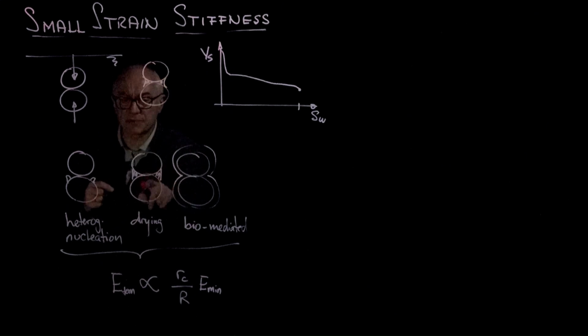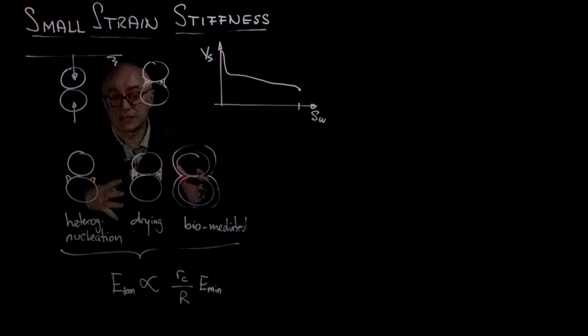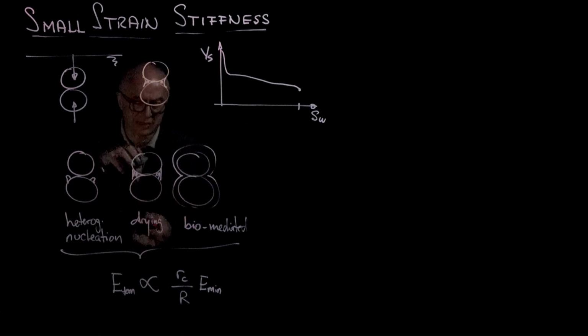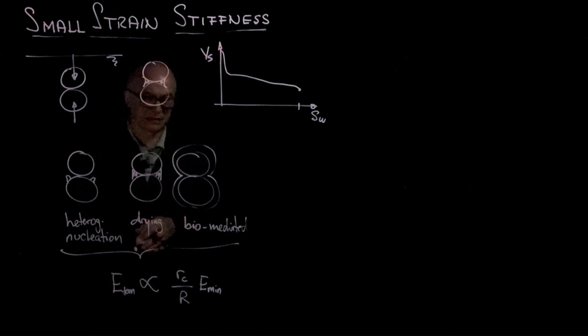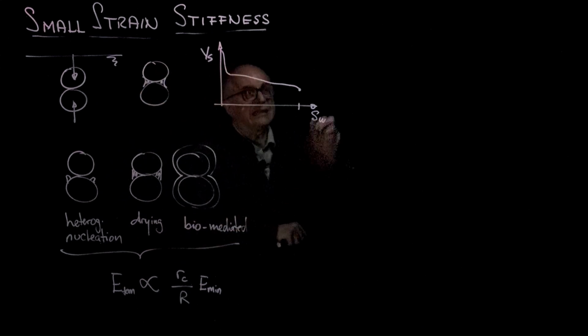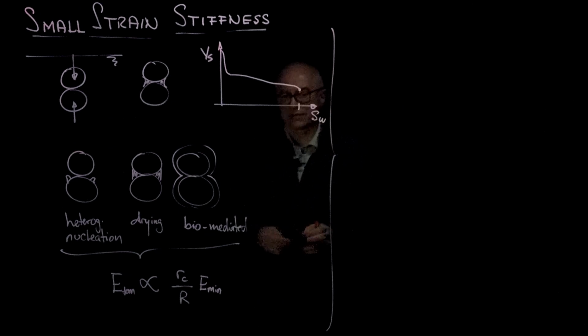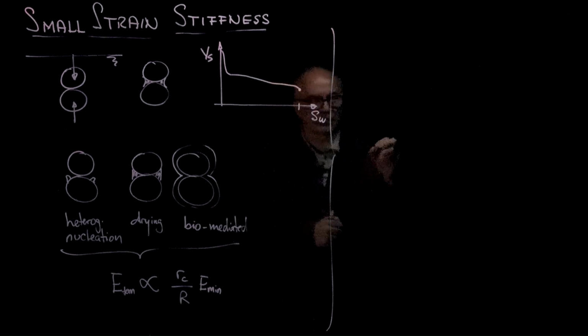So this type of cementation that happens biased at contact, typically during drying, it could also form by pressure solution precipitation at greater depth, will have a very large impact on stiffness. So now, with this in mind, let's look at the evolution of shear wave velocity or stiffness with respect to the loading and cementation history.